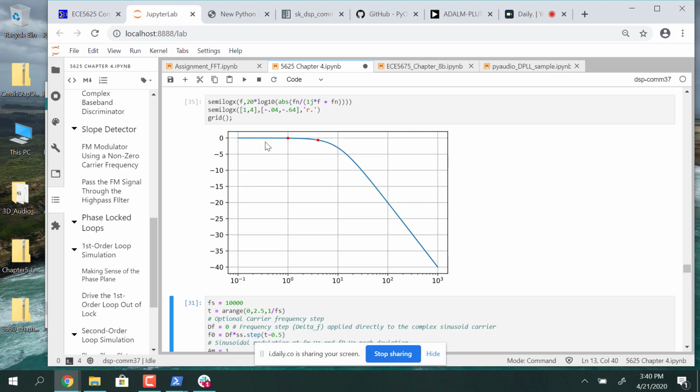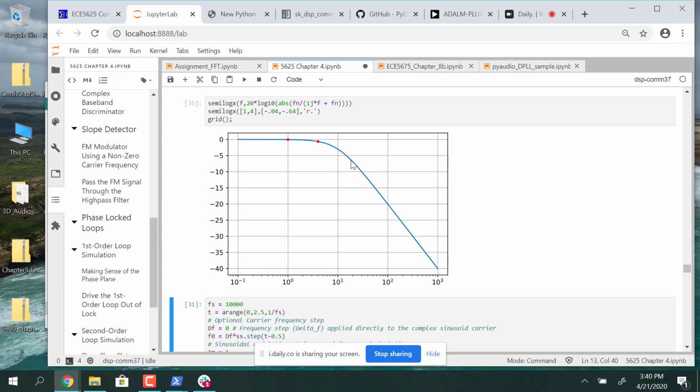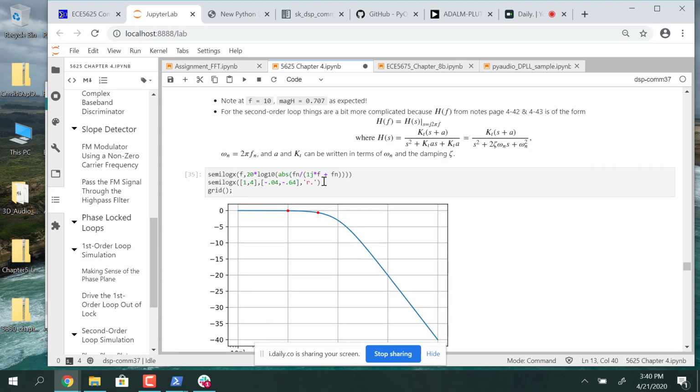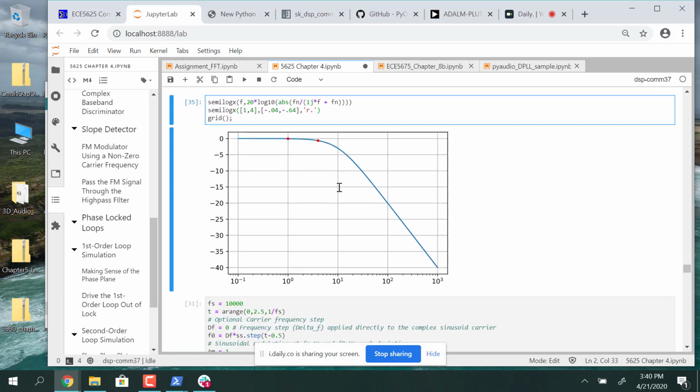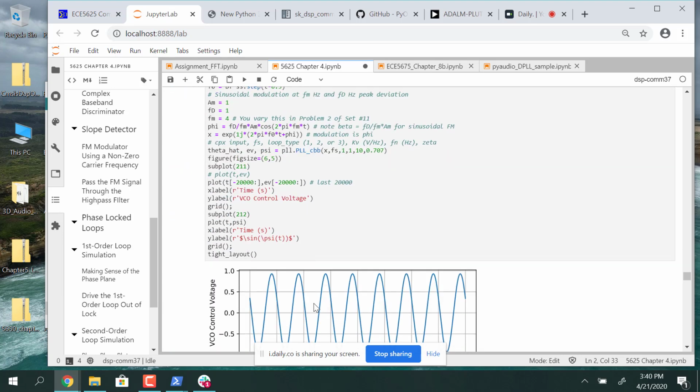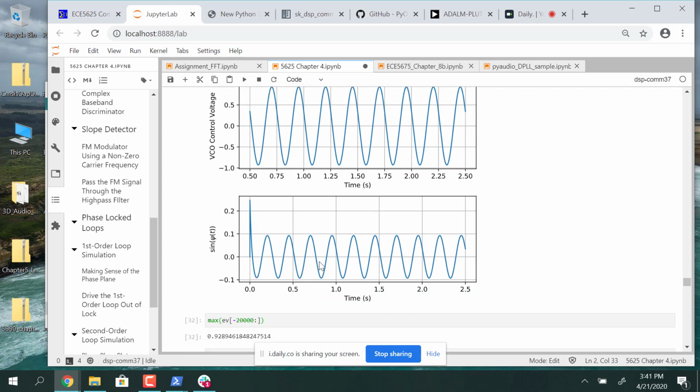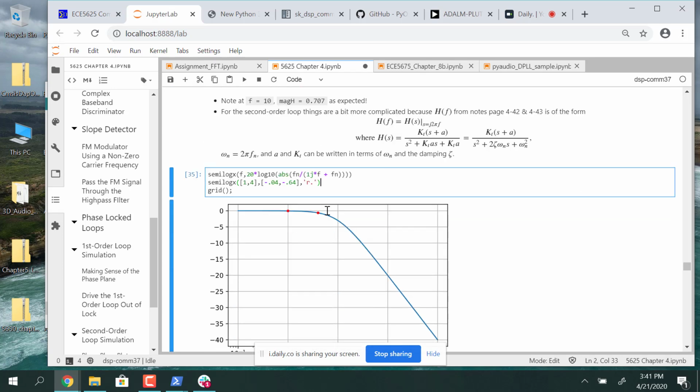You might run one at a lower frequency still, but then you can see how we're starting to fill out the curve. You don't need to have 100 data points, maybe 10 data points is about it, and you can collect them pretty fast. So what I would do is every time I run the code here and then convert it to dB, I'll kind of automate this a little bit, and then every time I get a new data point, I just start entering a new frequency value in that list and a new dB gain value in that list. And then the last time I run it, I will have a nice curve. I'll put some labels on the axes and so on and so forth. Look good?